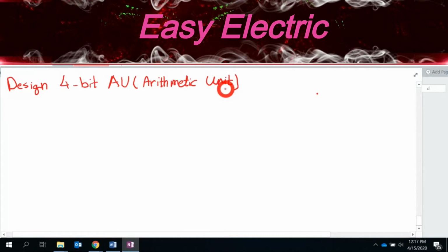Then you combine these two and you make the ALU. The ALU is the arithmetic logic unit. That's the unit that's able to do the arithmetic operations and also the logic operations. So we start with a very simple arithmetic unit, a 4-bit arithmetic unit. If we go into more detail about this arithmetic unit, I put a table here which summarizes how this arithmetic unit should work.